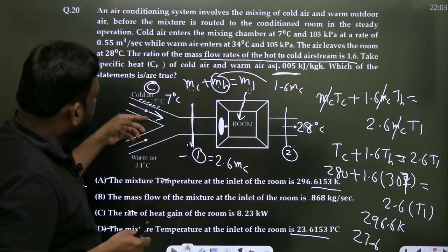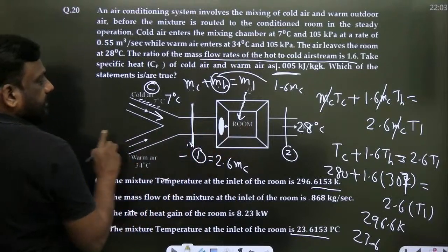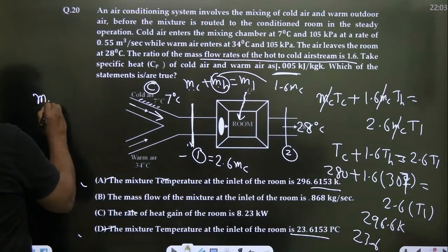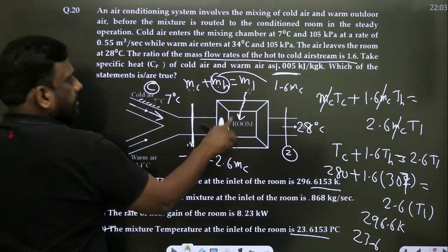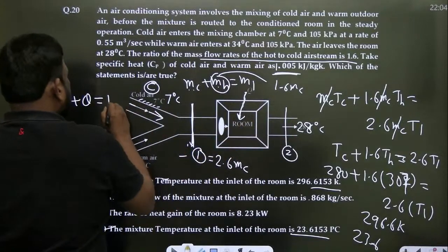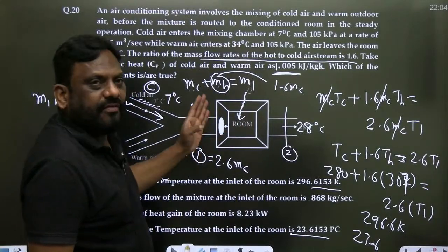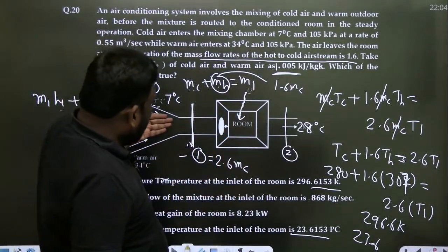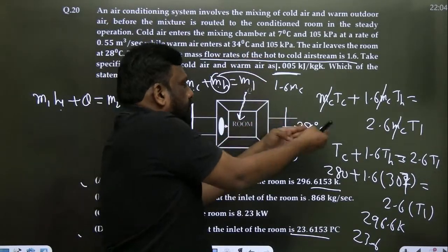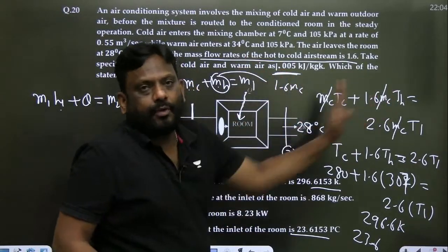एक बार देखना। So ये मास आ रहा है, तो अब बताओ सर, this is entering, ध्यान से सुनो, steady flow एनर्जी इक्वेशन अप्लाई करो, m1h1 plus q is equal to m2h2, इसको 2 ले लेंगे, बिकॉज इस रूम से कोई वर्क नहीं मिल रहा है। स्टेडी फ्लो एनर्जी इक्वेशन, एनर्जी एंटरिंग दिस प्लस दिस शुड बी इक्वल टू दिस, m1h1 plus q is equal to m2h2, he is asking